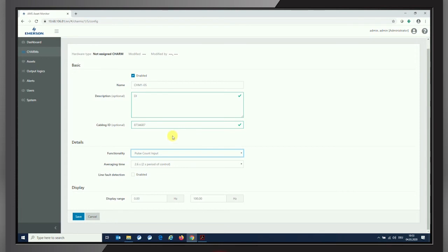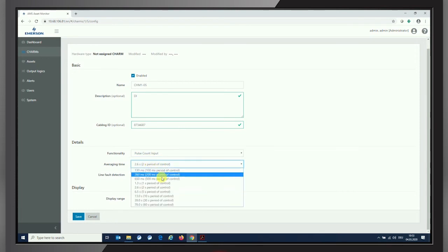So that only means for a period as specified over here, 130 milliseconds in range up to 60 seconds, that the monitor at 60 seconds would be counting pulses up to 60 seconds length and divide the number of pulses through the 60 seconds for referring with the speed information. So the speed information value will be updated every 60 seconds, which is a quite stable signal finally for a changing speed machine.